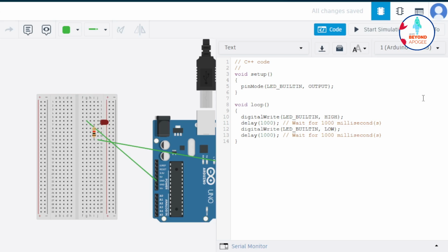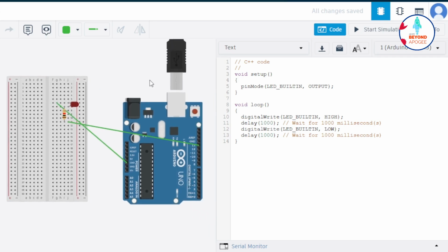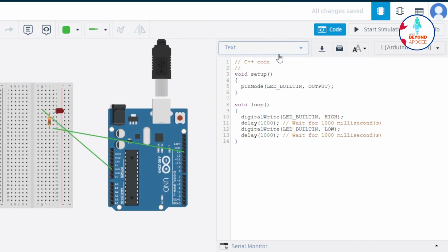Like we saw in chapter number 4 from last time, we can write Arduino codes in TinkerCAD using this text block. So we have the setup where one LED is connected via a resistor to the Arduino digital pin 13, and the other pin is connected to ground. We have written a code that lets us blink the LED every 1 second, that is 1,000 milliseconds. Now let's upgrade this code and try to include more than one LED and see what happens.